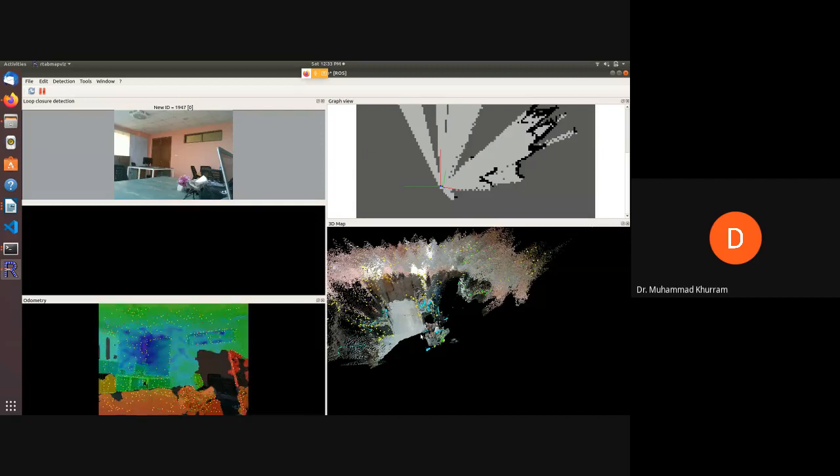So when the environment perception module, or environment mapping module, passes the value to the motion planning module, then we have ROS in place. In ROS, we have planners, motion planner libraries, and motion planning modules, and we can also write our custom motion planning modules. All those modules will be taking information from our sensor information, the one that we have just created in front of you using ROS, right? So these will be utilized in creating the mission planner. What is a mission planner?